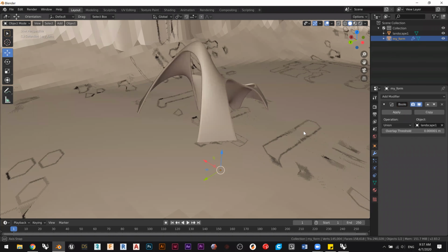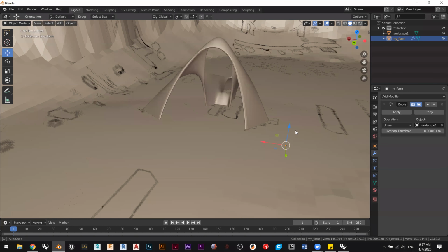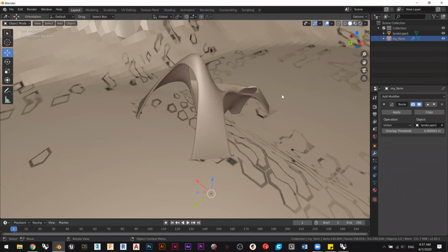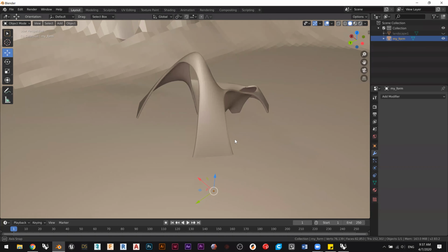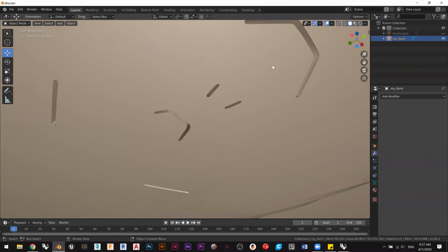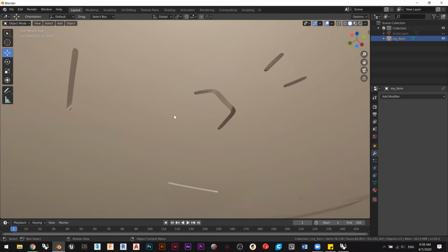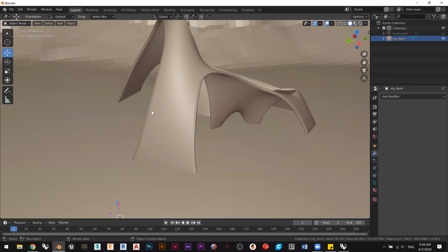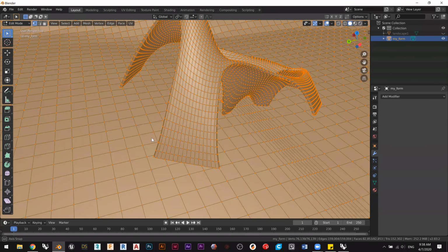So you can see we get the rave party again, and that's because the original landscape and the one that was joined to this are both visible in the same location, so it's making errors with shading. But if I apply the Boolean operation now, so I hit apply, and I hide the original landscape, you can see that now my form has a landscape connected to it. And if I look at it from the bottom, there is this clean joinery between the landscape and the form, right?